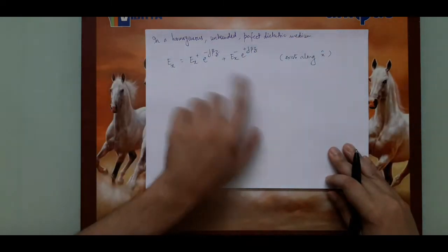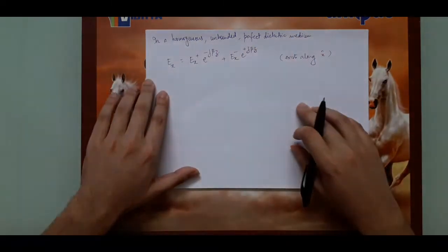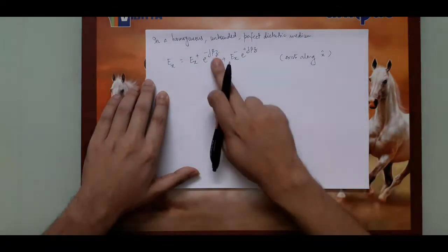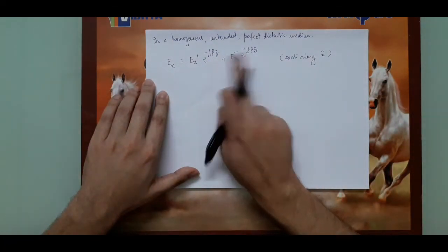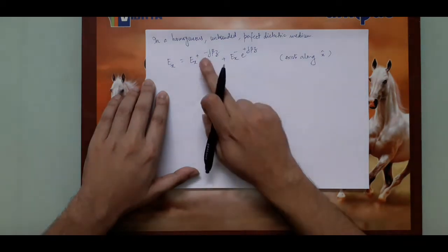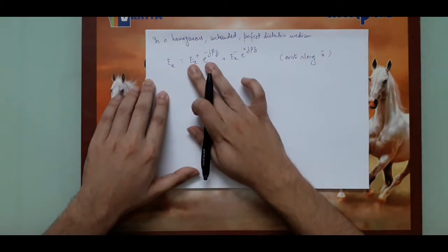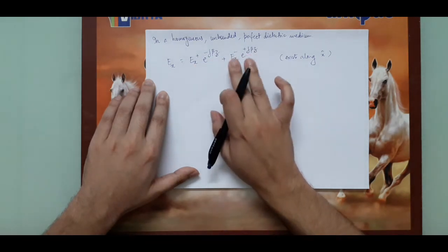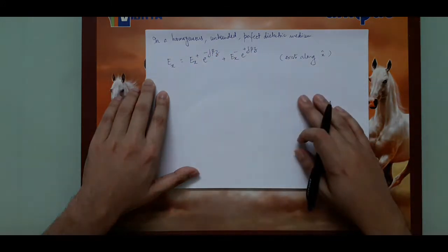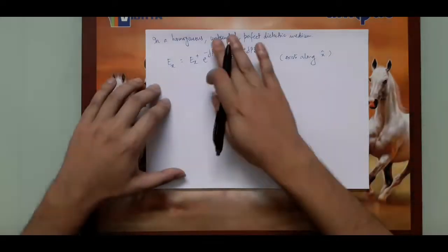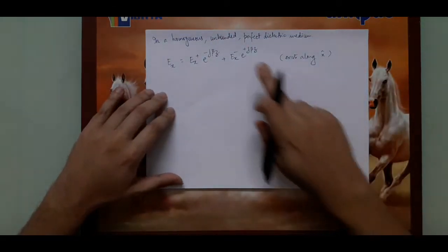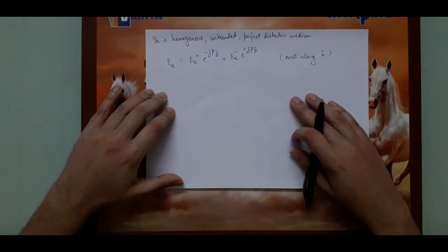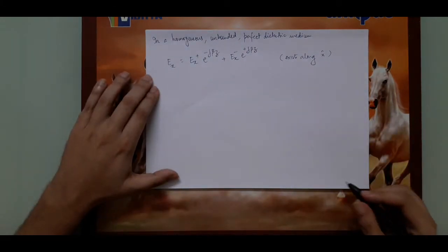So as you can see, this is very similar to the voltage solution on a transmission line, where the wave is essentially traveling along the z direction. This first component indicates the wave traveling along the plus z direction, and this indicates the wave traveling along the minus z direction. So in some sense, this is the backward wave or the reflected wave, and this is the incident wave. But if the medium is unbounded in general, then the second wave need not even exist, because there is nothing from which the wave will be reflected.